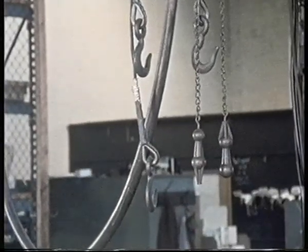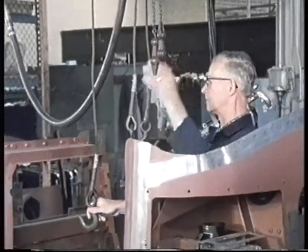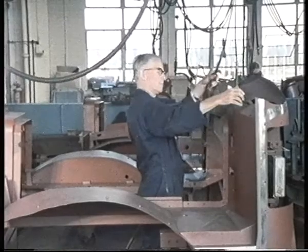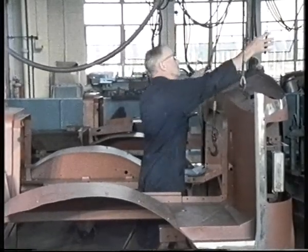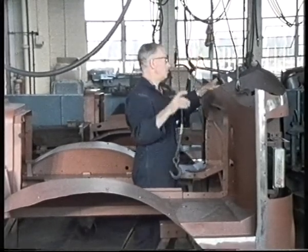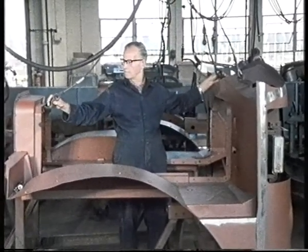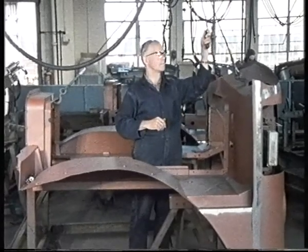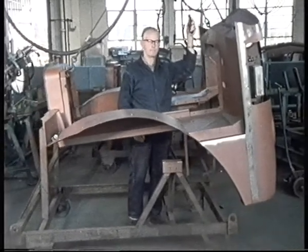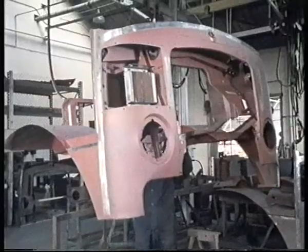But why? Like the bar, this assembly is heavier at one end, although this time it's heavier on the right. If we used slings of equal length, it would tend to tip until its center of gravity was directly beneath the hook. By using slings of different lengths, the load hangs level, even though it's heavier at one end.